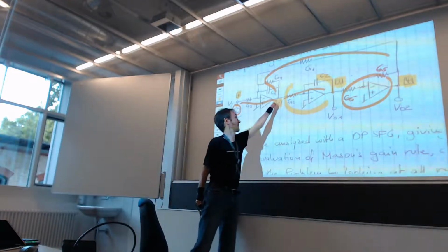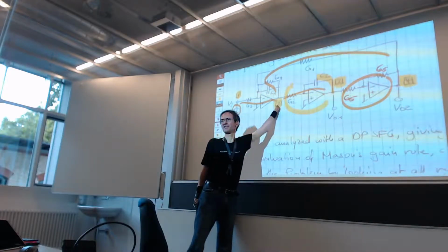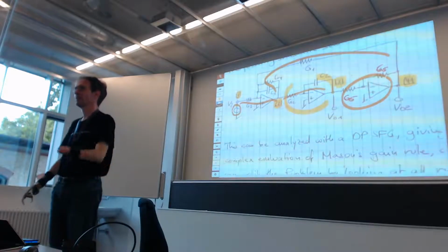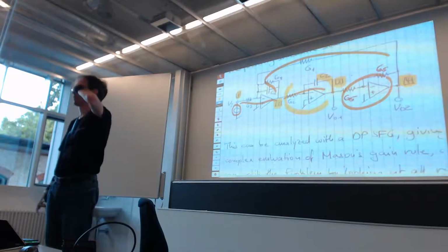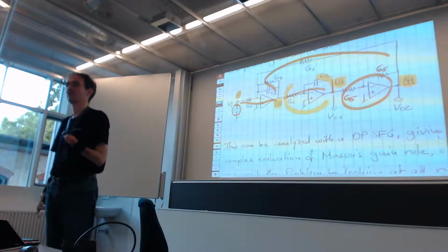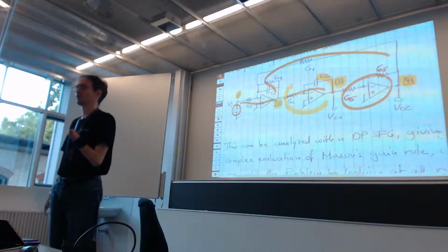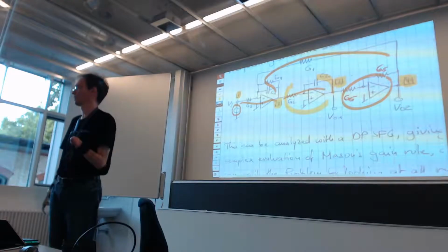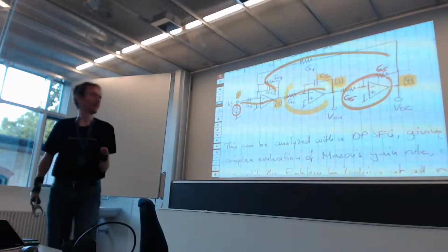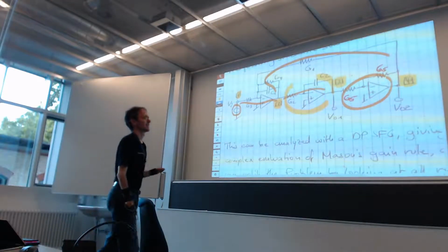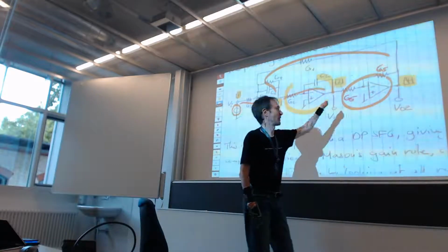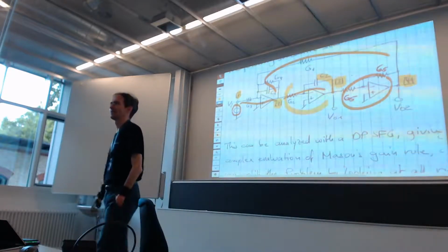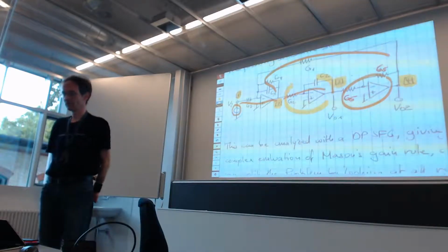Then you have a low-pass filter. But if you take this here as the output, which you can, because it is, after all, the output of an op-amp, it can drive something more, then you also have a bandpass filter. So with the same filter structure, you have two filter functions available with two different outputs. So at least from using op-amps and sacrificing a full op-amp to get the gain of -1, you win something. And that's one of the advantages.